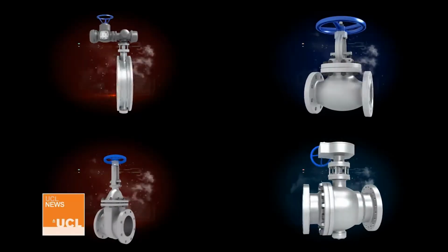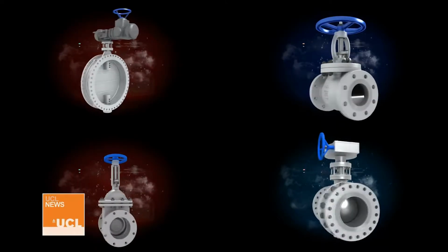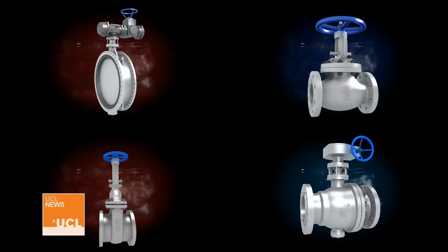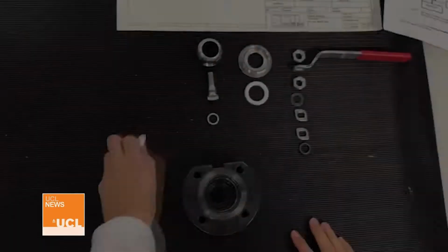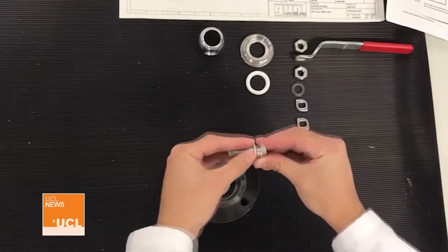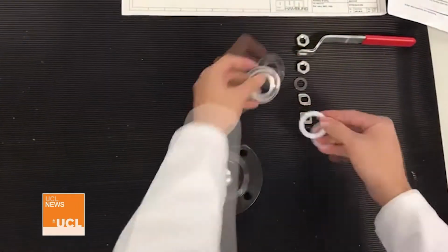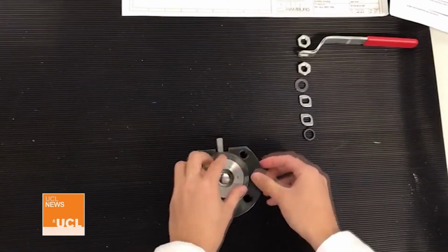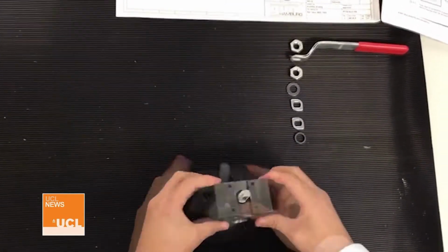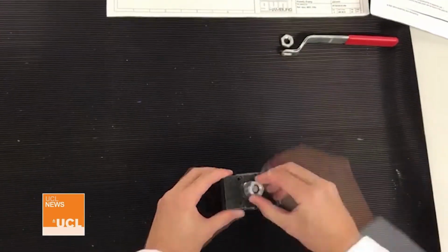A valve is a device that can alter the flow of fluids in a process, and the exact use depends on the type and geometry. In assembling the ball valve, we begin with the housing. Firstly, insert the spindle and align such that the ball locks in place, and close using the ball seal. Then finally, we close the spindle up with the hand protection at the top.